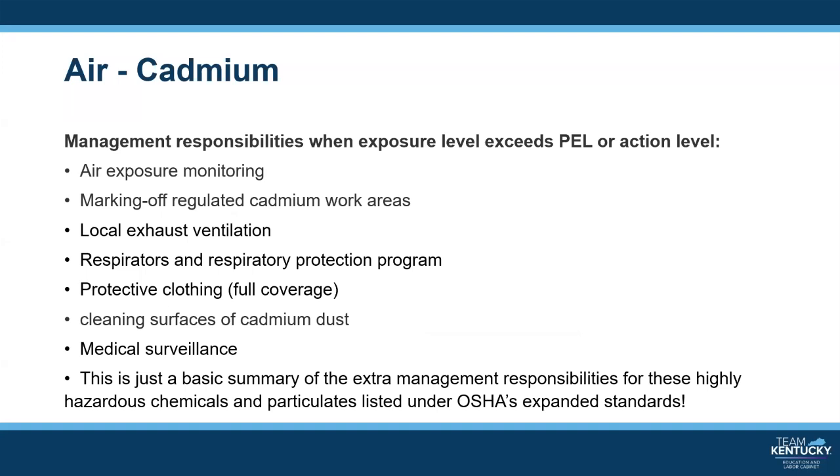This would include air exposure monitoring, marking off regulated cadmium work areas, could require local exhaust ventilation, could require respirators and a respiratory protection program. It could require protective clothing for the employees, which would be full coverage clothing.